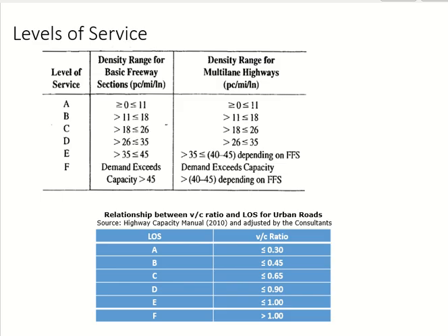If there is rain, medium rain, for most of the times the pavement will be wet and the visibility will be lesser, and so the speed will be lower. When the speed is lower, density is high. You can see density is high. But it does not shift the traffic too much from one condition to the other. These things are increasing, but within the same range. Clear?